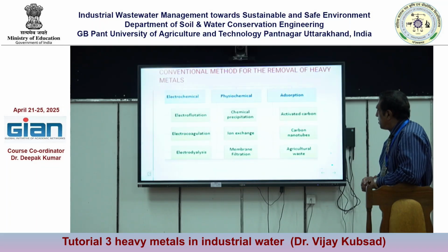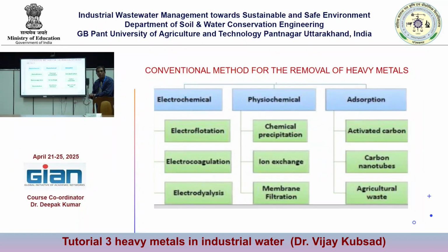Then physicochemical: chemical precipitation, ion exchange, and membrane filtration. Right? There are methods where you can do adsorption: activated carbon, carbon nanotubes, agricultural waste.